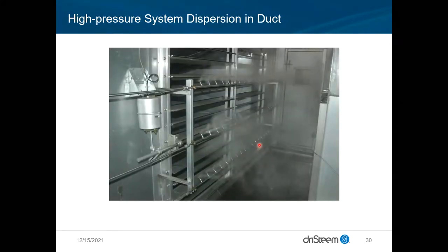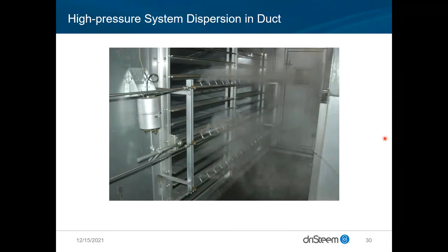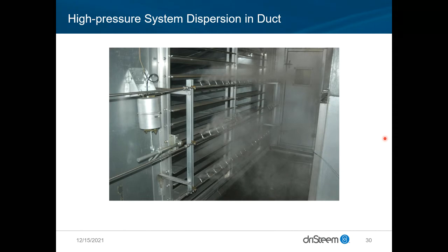Just want to show real quick an evaporative option and how that could get installed. You see that we again use nozzles, but these are wet systems in the duct. That's the most important thing to keep in mind, whether you do it air handler or duct. These systems, you're not going to have enough distance for complete evaporation. You're going to have 50, 70, 90% of it absorbed. The rest of it's going to get caught by a mist eliminator and drained.